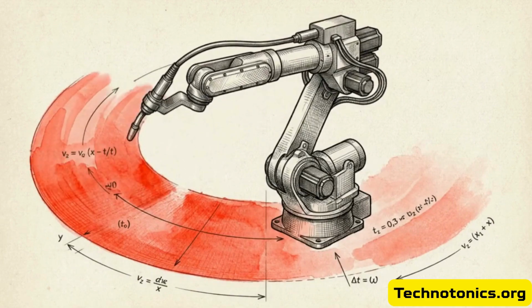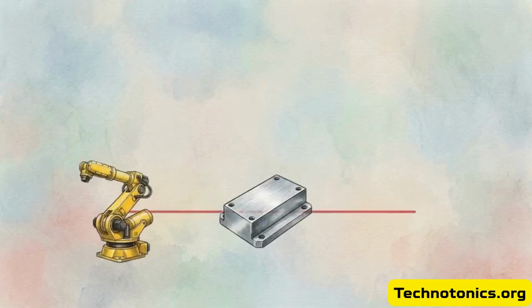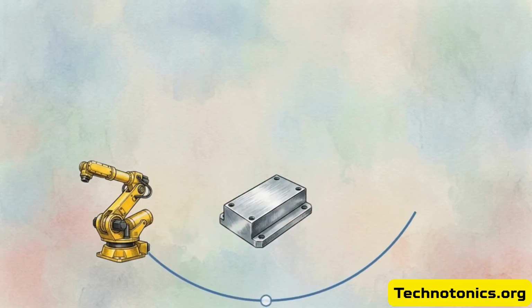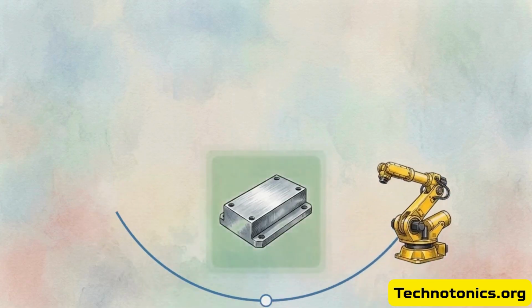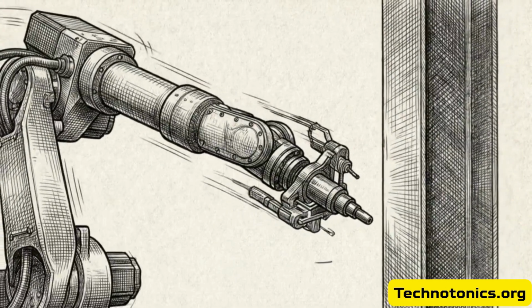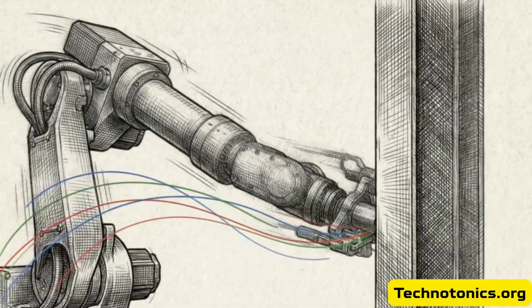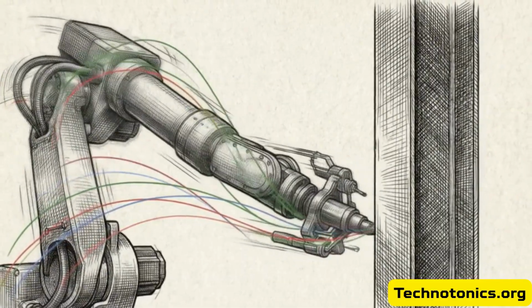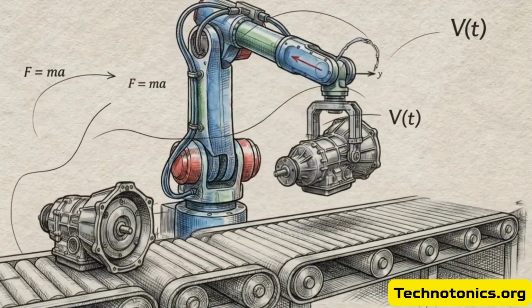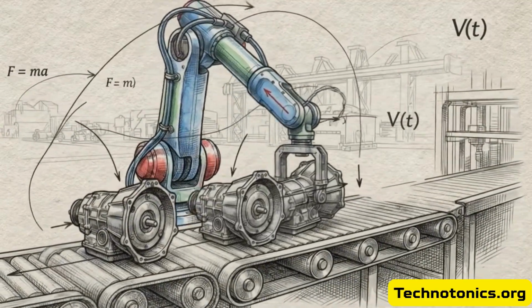The interface visually pinpoints exactly where the interference occurs. From there, you simply adjust the problematic waypoint or alter your approach speed. You run the check again until the path is completely clear. Taking the time to run this proactive digital checkpoint guarantees the robot will clear its surroundings, eradicating the risk of destroying physical equipment. Run through all 5 steps, and you get an error-free robotic workflow. The machine operates continuously and efficiently because the instructions are perfect.